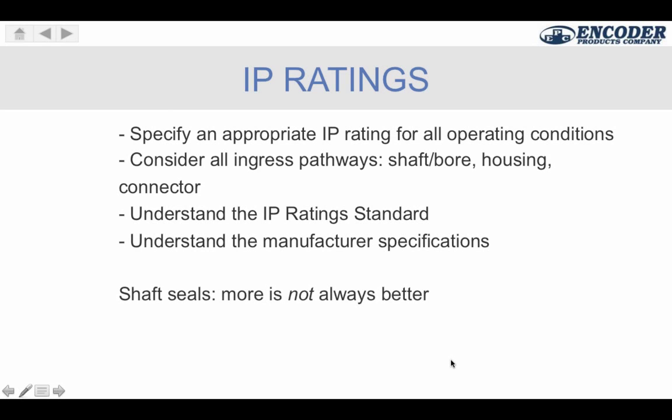More is not always better. When it comes to shaft seals, a higher shaft seal IP rating will increase the breakaway torque and also can produce some heat over time, particularly at high speed. So the IP rating does have some potential unanticipated consequences. So more is not always better.